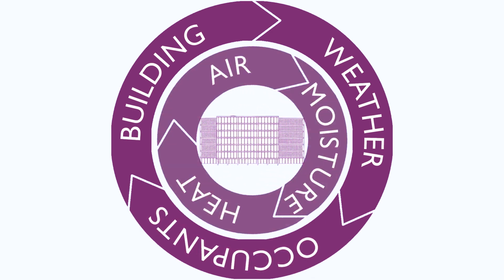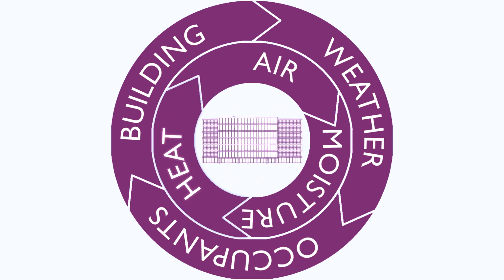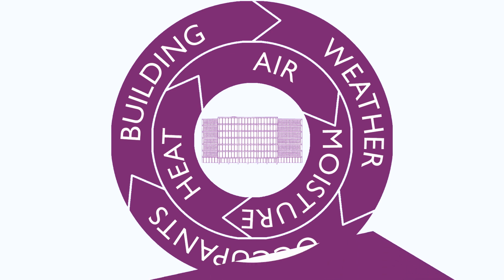The influences of these three aspects can then be assessed in terms of heat, air and moisture movement within the building. This takes into account the heating of the building, as well as the air leakage effects and response of the building fabric to the absorption and desorption of moisture. Factors such as the position and performance of the fabric insulation can also be considered.